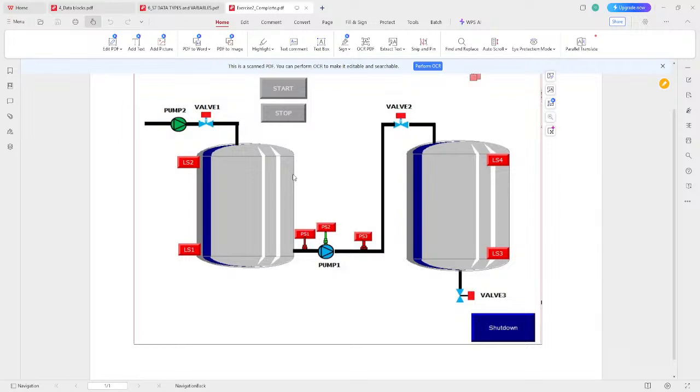Okay, so before the valve comes on, I'm going to be designing a block, like I said, a pump control block. These are going to be the inputs of the block. We're going to have the start, we have the stop. We have start, stop, we have dry run. We have status.